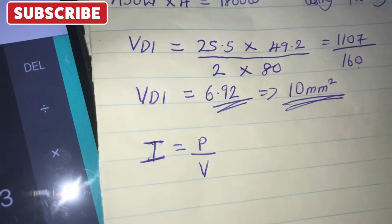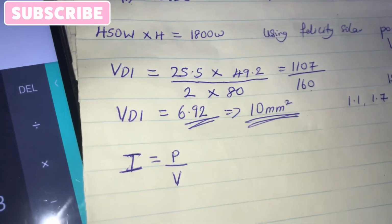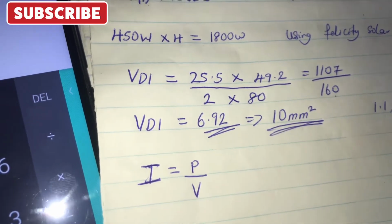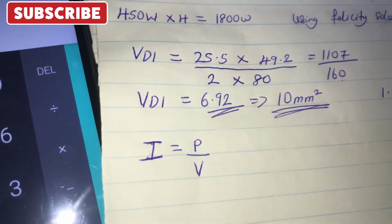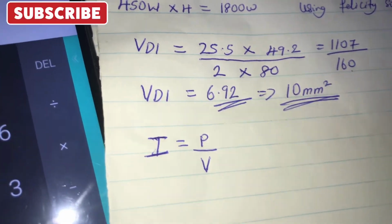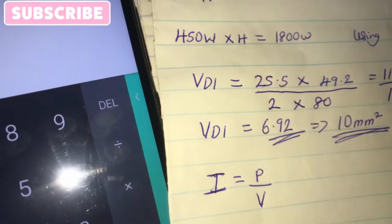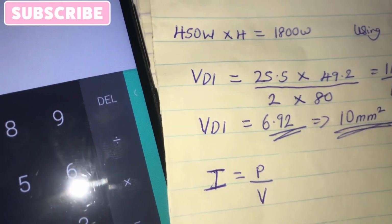But in this case, we don't even know the value of the current passing through the wire, that's from your charge controller to the battery. So we have to first of all find the current that will pass through the wire before we substitute it in our equation. So knowing that I is equals to P, power, over voltage.